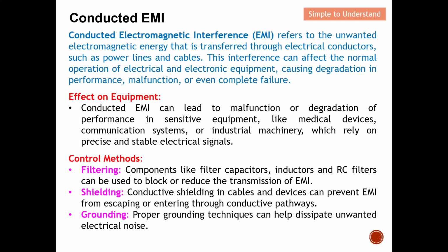So basically, we need to ensure, for example, for the medical device, let's say noise enters through the power supply. The power supply becomes unstable, and this can be an issue because the medical device can be reset, and this can be a catastrophic effect here. Some of the controlling methods: filtering, using components like filters, capacitors, inductors, and RC filters, which can be used to block or reduce the transmission of EMI.